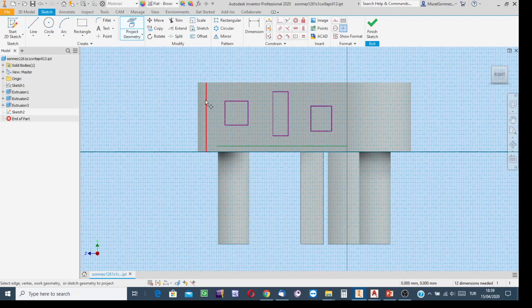With respect to this boundary, with respect to that projected line, I'm going to anchor the sketches and thereafter size them. Dimensional constraint. From the projection of the edge of the floor of the platform,